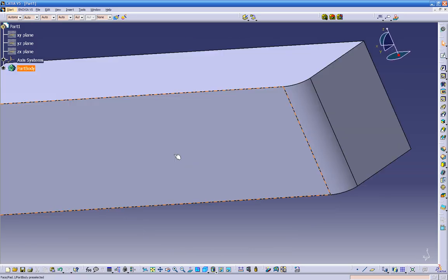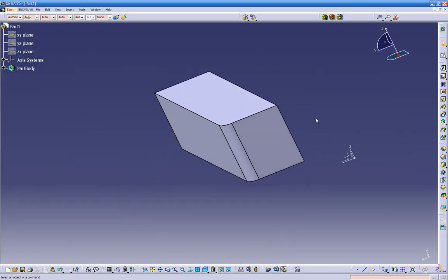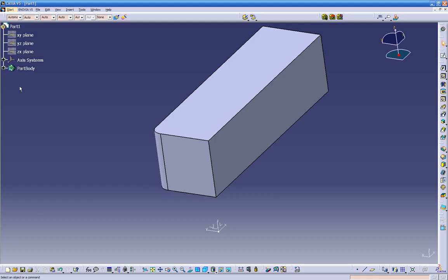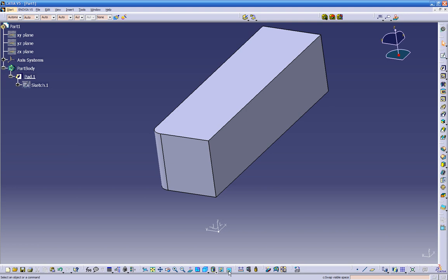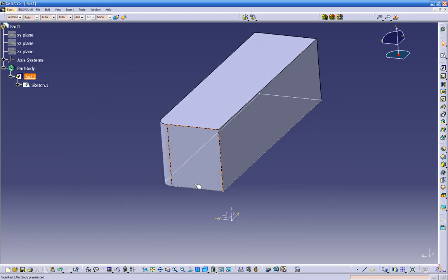We can add fillets to the pad on the 3D mode view. So we can create on the sketch view, see over here on the sketch, if you right click and turn it on, you can turn it off, turn it on. What it does is put it on a no-show level, which is up here. Okay, so we can bring it up again. We could have put a corner radius into the sketch, but we can do it also on a 3D view.